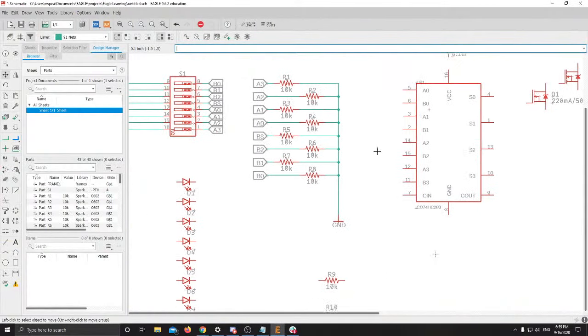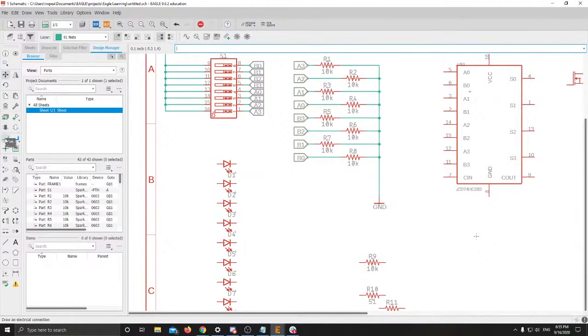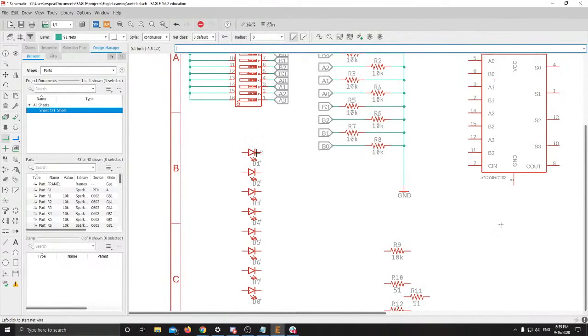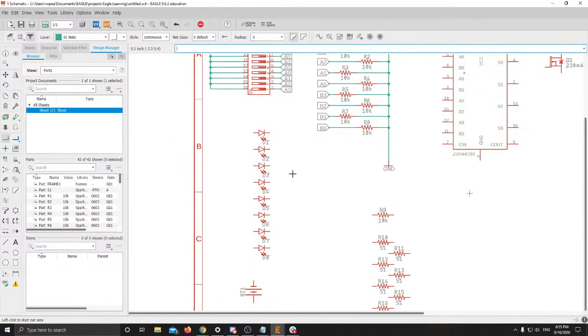You can do it that way, and how you do it is you just come over to the net tool, and you'd do something like that. You'd want to route it a little bit better. Also, if you want to rotate how it's routed, like the angle that it does, you can right click and it'll try the other way. I'm just going to go ahead and add labels like we did for the resistors, because I think that's a little bit easier, but you can do either approach.